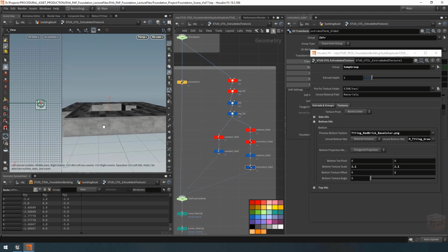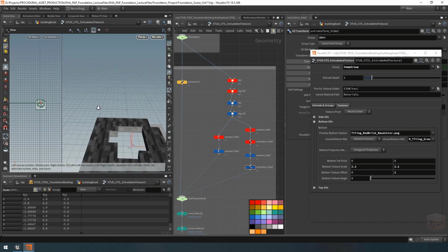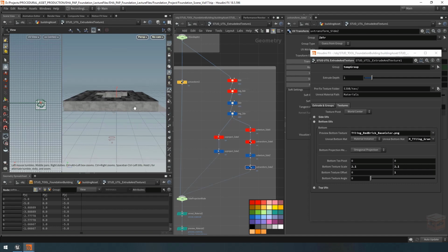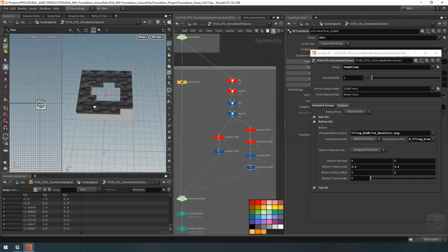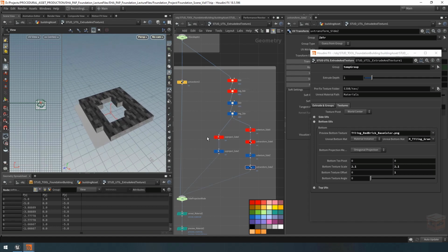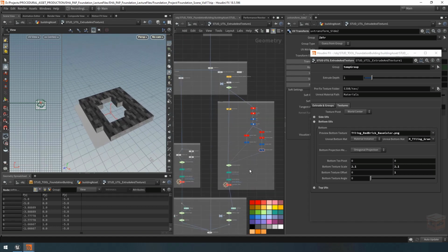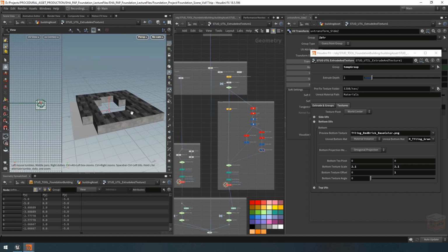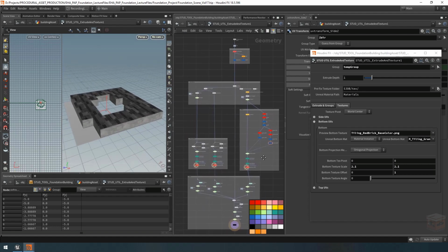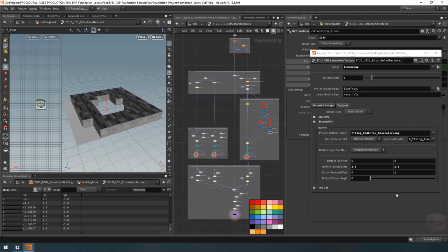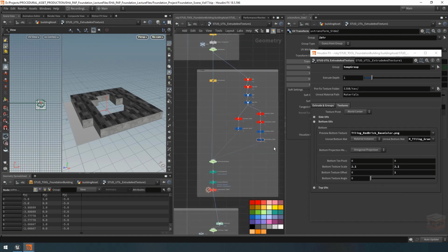So in other words, this texture here is going to be a mirrored projection of the texture on the other side, which means that one of these two UVs is actually reversed, right? If you want to fix that, go ahead. It's something to keep in mind, but I'm not going to bother with it in this case. I don't need it in my project. If you do, then feel free to duplicate some of these nodes and reverse them and fix that.